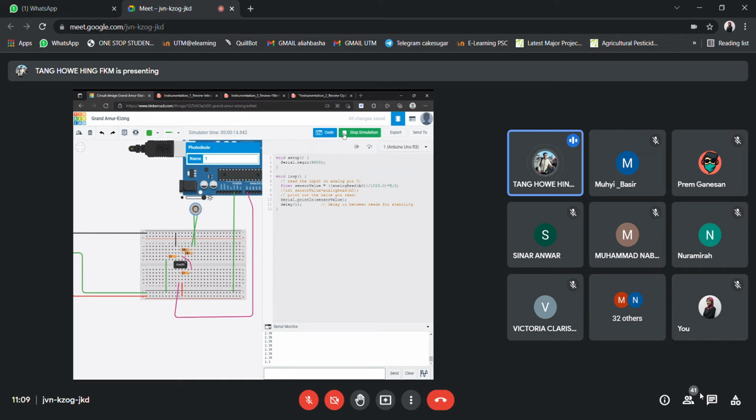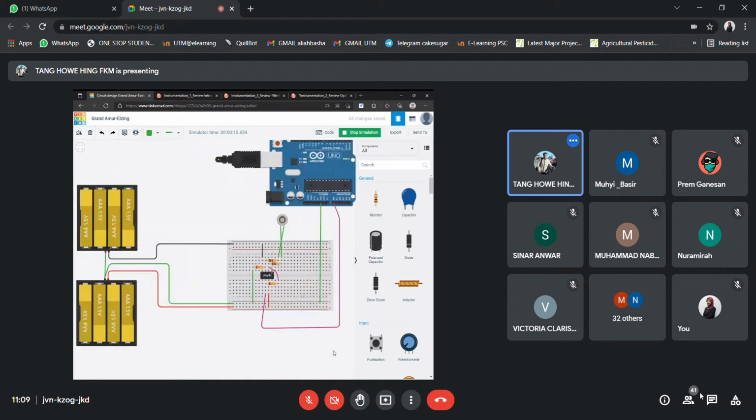The main reason why it is so difficult is simply because this op amp has to be dual supply. So it needs to have a positive and a negative power supply. And therefore, you can see that once it is a dual power supply, this supposedly has a voltage somewhere around 3 volt. So we are actually connecting 3 volt to this ground. I'm not sure what the impact of doing this is in real life.